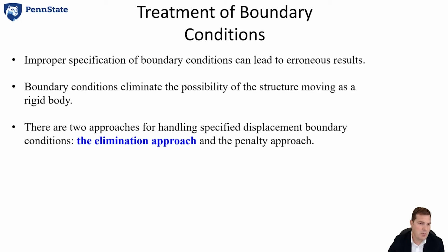Boundary conditions are really important. Improper specification of boundary conditions can lead to errors in your solution. We're going to see with a couple of applications how sensitive the problem is to boundary conditions. I can't remember the app, but we actually do a crushing tube problem where you get to really see the effects of boundary conditions. So you have to be careful about that.